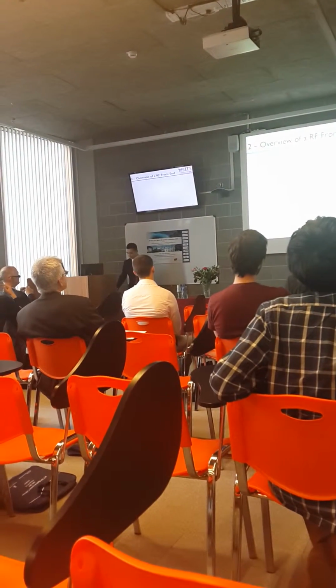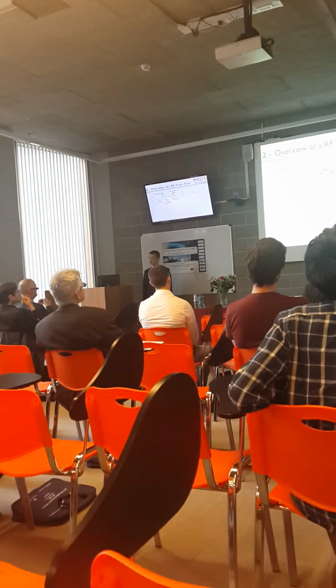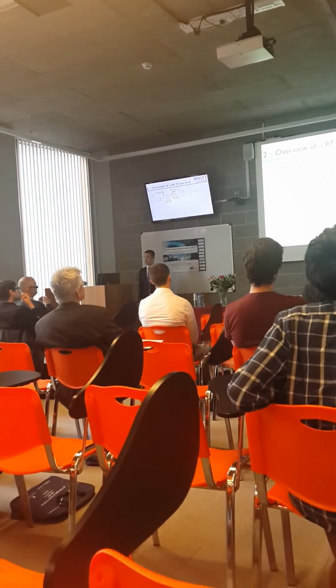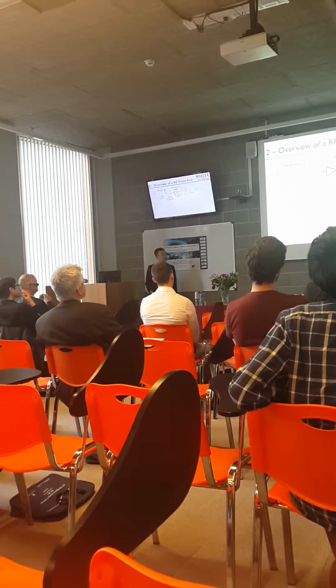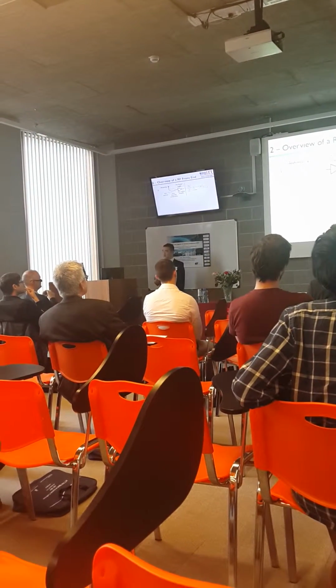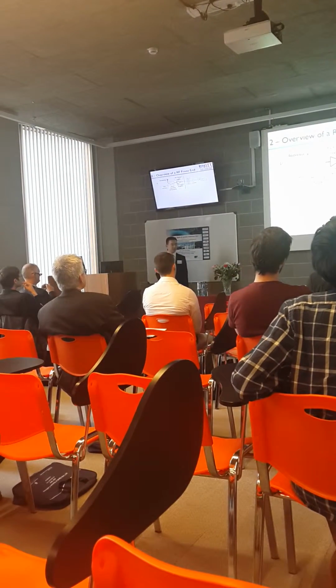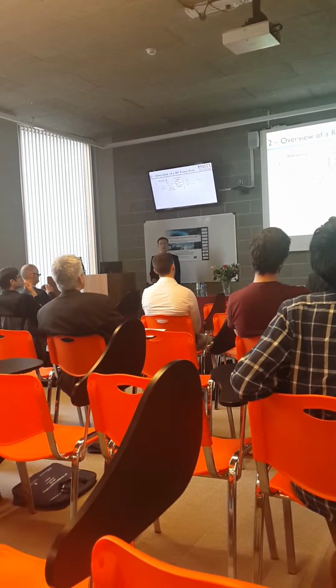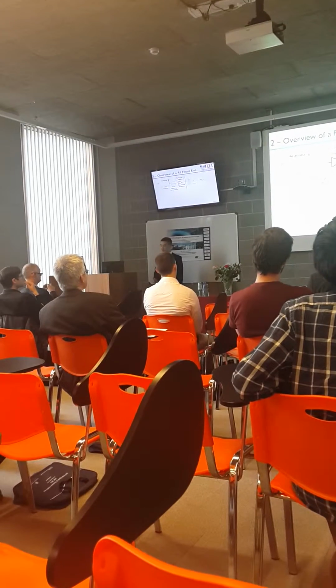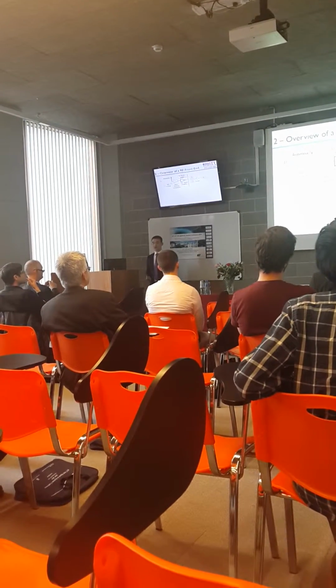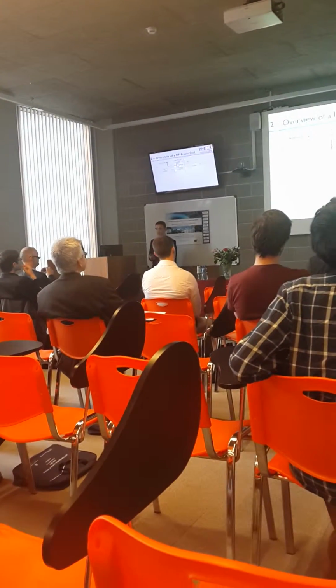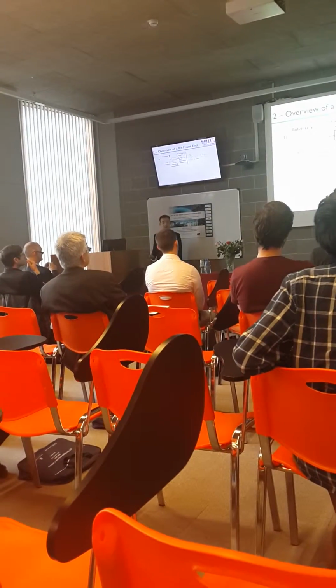The RF receiver front end block diagram is shown as figure 1. The antenna and the low noise amplifier would normally be designed as a 50 ohm impedance to get the maximum power transferred, and the filtering and matching components in the middle would introduce path loss for the low noise amplifier.